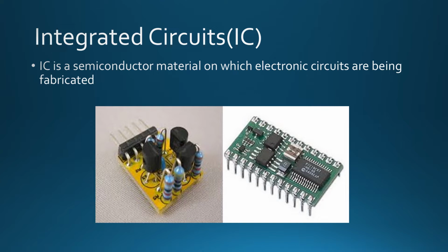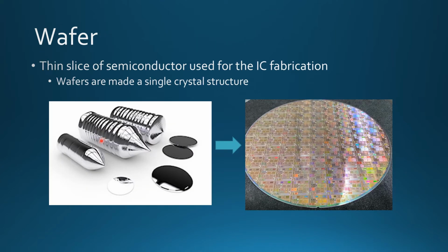So right now, let's briefly touch upon how we build an IC. All ICs are manufactured from a single crystalline structure called a wafer, which looks like a mirror, and these wafers are sliced from a big crystalline structure as shown in this picture. ICs are fabricated on these wafers, and each segment of an IC is called a die, which will eventually be cut out and go for packaging. So that's how we get an IC: it is fabricated on a wafer and we slice out each die from the wafer.